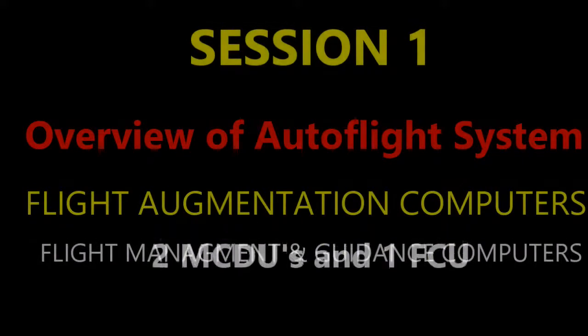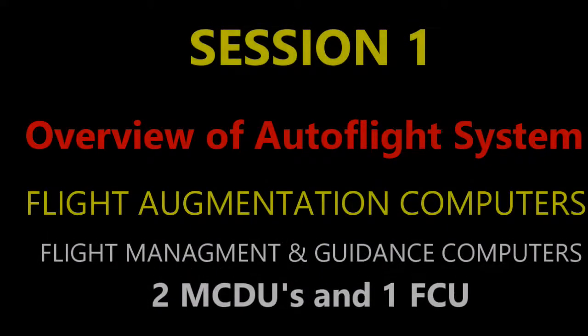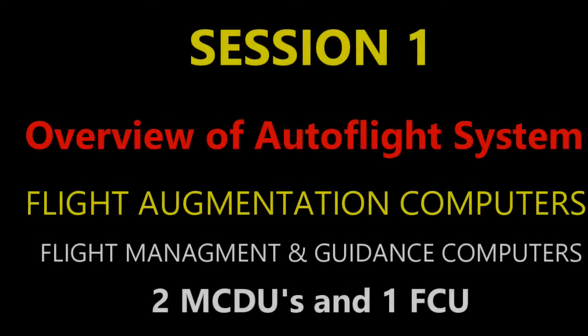Okay, you also have 2 navigation displays. Those are on the main instrument panel. So MCDUs are on the center pedestal. Navigation displays are on the main instrument panel. And the other thing that you find on the main instrument panel is the primary flight displays. There's 2 of those. So you got primary flight displays and navigation displays on that same main instrument panel. But the MCDUs, your multi-purpose control and display units, are located on the center pedestal.